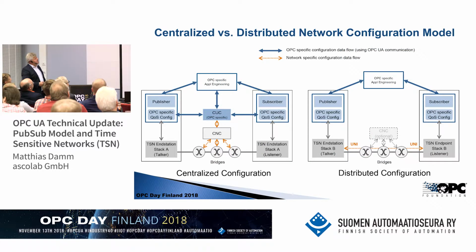And the streams contain addressing information, but also timing information. And so this is what we work on in the OPC working group for the TSN parameters: to represent these TSN constructs and the quality of service parameters in the OPC UA PubSub configuration model.